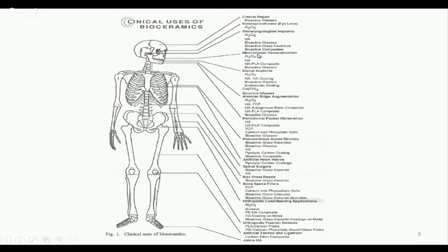I think our group at the University of Bristol, one PhD student, Singh, was boiling the alumina with sodium hydroxide and he was able to make it bioactive. So basically, if the alumina surface has a lot of OH by boiling with sodium hydroxide, this OH will be the nucleation site for calcium, and eventually as you dip it into SBF, it can have bone growth on the surface of alumina.